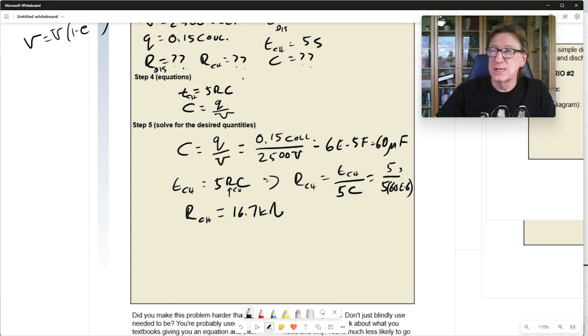So you could put in series. We've got 10K resistors in our kits. We've got a 5.1K resistor in our kit, and we've got a 1K resistor in our kit. Well, right there, you've got 16.1. So you need another 500 ohms or so. So take a 220 and a 330. You see that we can just build whatever we need if we need a precise value for that.